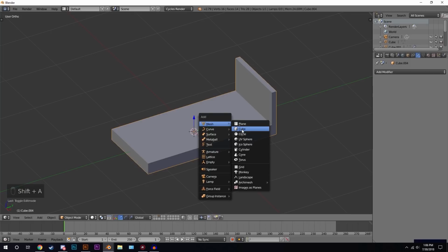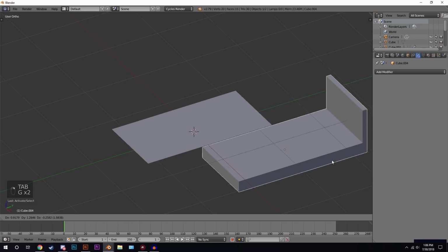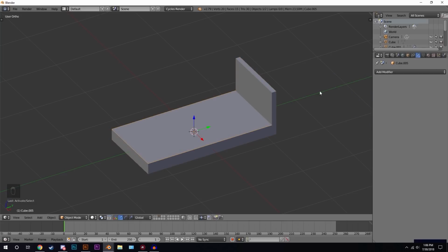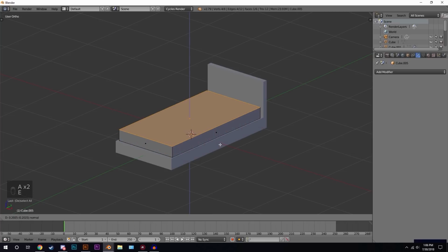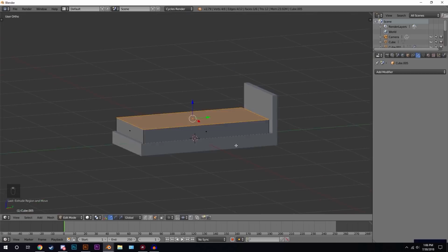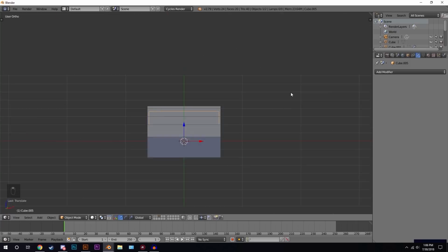Next, we're going to add in another cube. Actually, we can delete that. We'll just Shift D this face. So right click on this face, Shift D it, then press P and go selection. So now we have two different objects right here. With this face selected, I'm going to scale it down a little bit and go into edit mode, A to select it, and then extrude it upwards. Probably around the same height as the bed frame itself. I think that'll be good. And then just drag it over to the right till it touches that headboard.